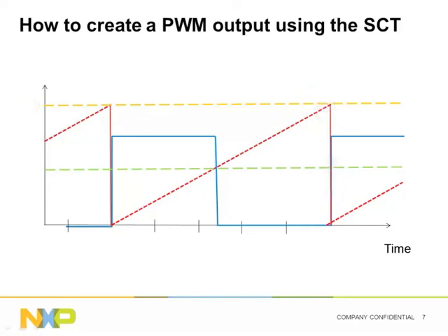This, of course, is just a simple example. Since every event is fully configurable, you can define whatever action the hardware needs to perform on the outputs, like setting, clearing, toggling the output, or also no change.